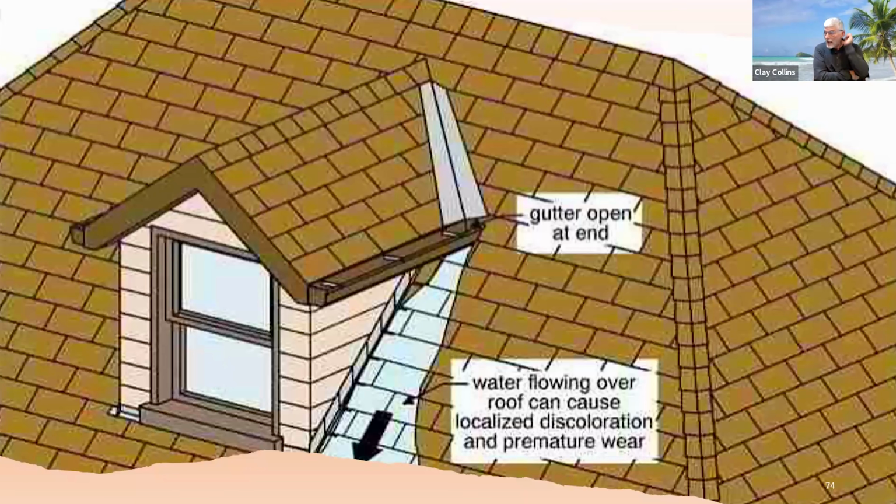I know they're going to put the downspout and have it run down the roof to the lower gutter system, or they're going to have more downspouts following the outside of the wall. In one particular case, I counted that it would take 8 downspouts to do it properly, so that this didn't occur.